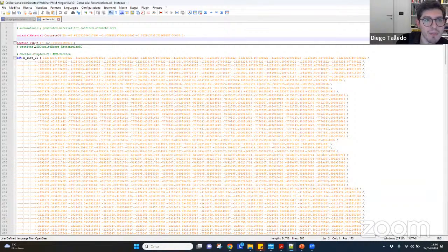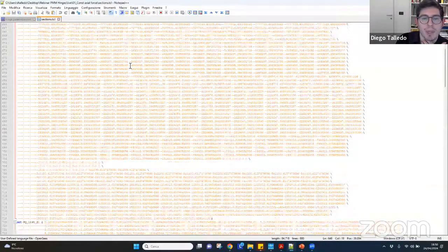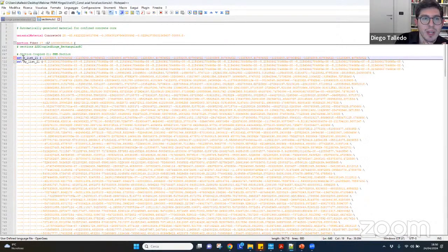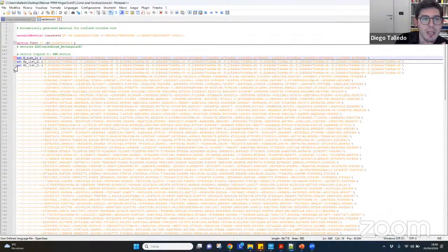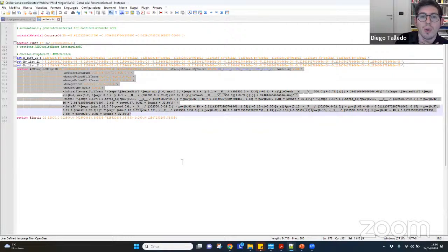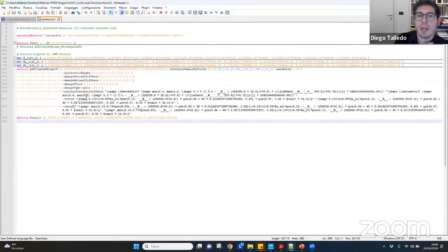Okay, and this is our fiber section. I close it. And then we have this structure domain that I mentioned before. So you see, it can be quite cumbersome to insert these values in OpenSees. So STKO has this big advantage that creates for us N list, MY list, and MZ list. And this is our OpenSees code for creating our section. So this section contains the parameter that we mentioned before.